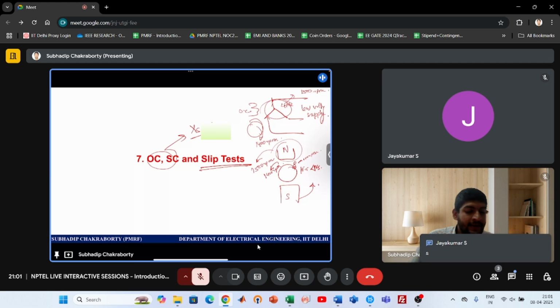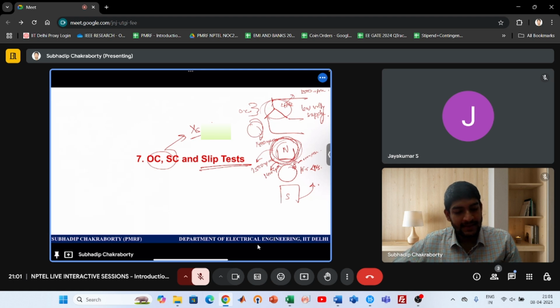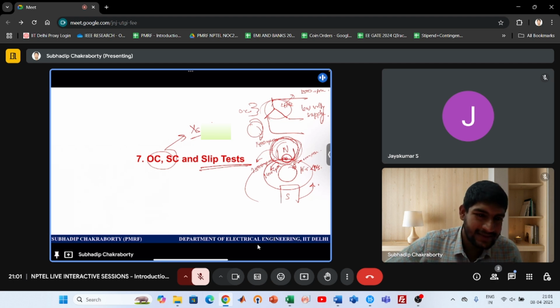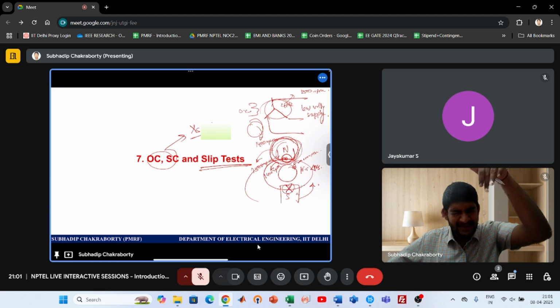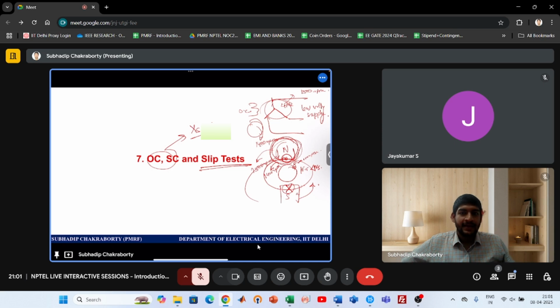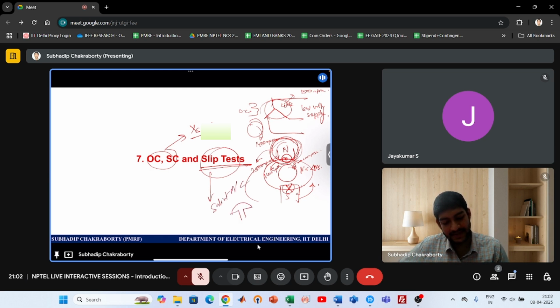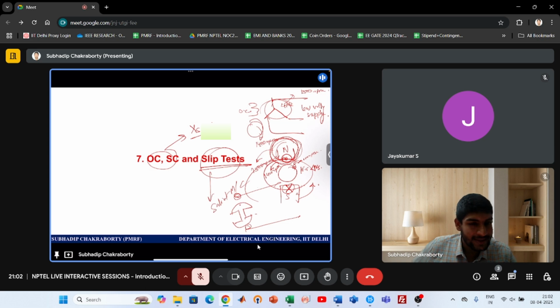Now, another important piece of information is that this rotating MMF cuts the red phase conductor, RYB as they generally say, that is a 3-phase machine, right? At that point, the voltage is maximum. But this test is generally conducted for salient pole machines, where the shape of the field pole is like this. So when it is like this, the A phase, since it is already connected to a supply, will draw less current or more current. Can you tell?